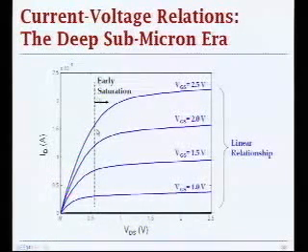So you enter this early saturation region. What's going on here is that once your channel is shorter and shorter, and you keep applying a large electric field over that channel, then eventually you will hit the limit, and your carriers will be velocity saturated. So that's the most important phenomenon that we need to understand for these deep submicron transistors.